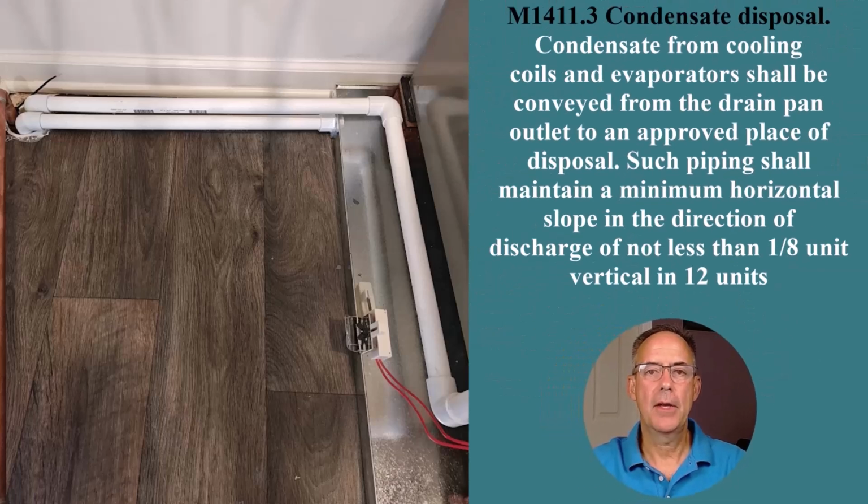M1411.3 of the mechanical code talks about the condensate line, and it tells us that that condensate line has to have a slope of a minimum of 1/8 an inch per foot.